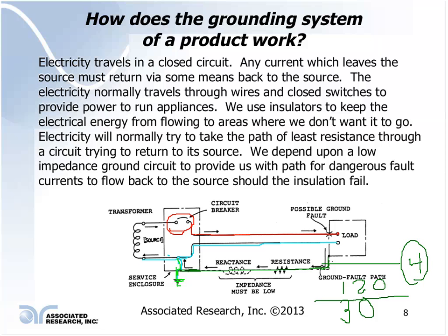So right away that gives me an idea as far as what the maximum resistance of my ground circuit has to be less than. If it's greater than 4 ohms, then my fuse or circuit breaker will never open up. One thing to keep in mind, fuses and circuit breakers are not designed for shock protection.